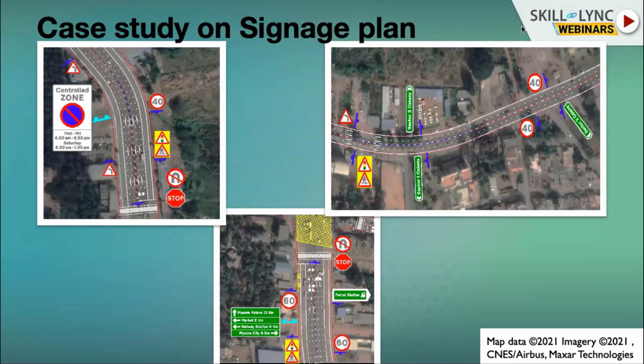In the third zone, this is a minor road when you compare it to the major road. This junction has a major road and a minor road. The major road is the one with a divided carriageway, with a 4-lane carriageway. The other one is an undivided carriageway, minor road. You can also observe how the design speeds vary and how they have been imposed, due to the category of the road or the restrictions from the geometric parameters.